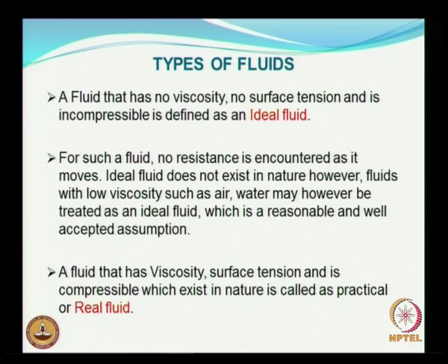We basically have two broadly classified types of fluids. A fluid that has no viscosity, no surface tension and is incompressible is termed an ideal fluid. For such a fluid, no resistance is encountered as it moves. Ideal fluid does not change in nature. However, fluids with low viscosity, such as air and water, may be treated as an ideal fluid, which is a reasonable and well accepted assumption.